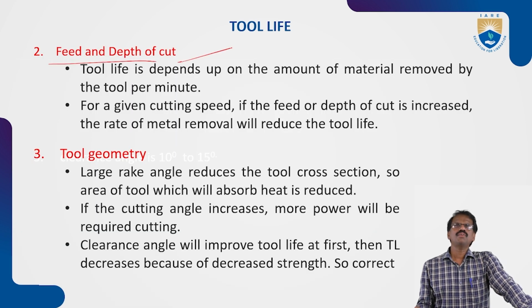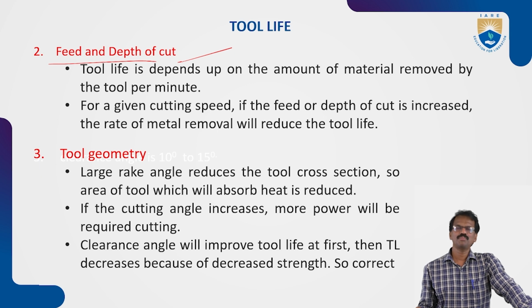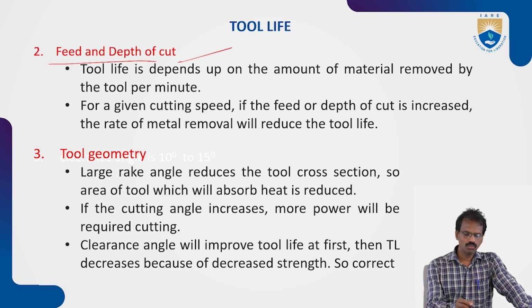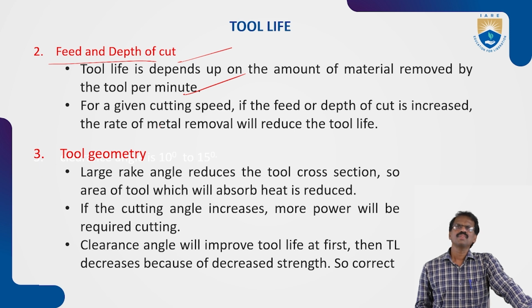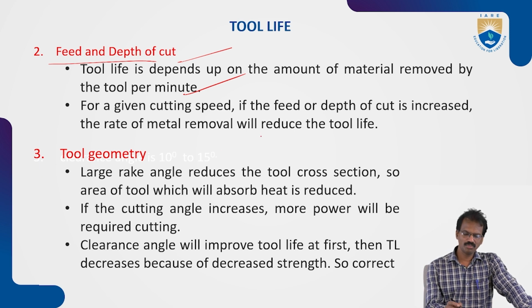Tool life depends upon the amount of material removed by the tool per minute. So for a given cutting speed, if the feed or depth of cut is increased, the rate of material removal increases, so it will reduce the tool life.